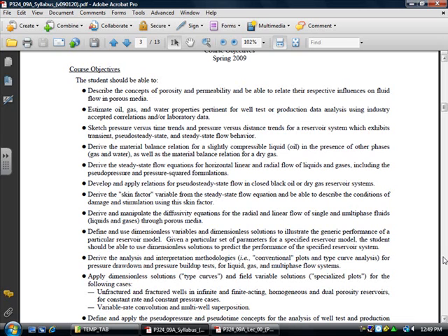So let's talk about that for just a second, very quickly. Ready? Landon? Ready? Okay, so I'm going to take some magic paint, and I'm going to paint a skin on the inside of the wellbore. Can you imagine that skin will cause a positive pressure drop, that it will choke the well? If I keep putting paint, will it make the pressure drop larger between the formation and the wellbore? Yeah, that makes sense. So as an impediment to flow, the skin factor makes great sense.